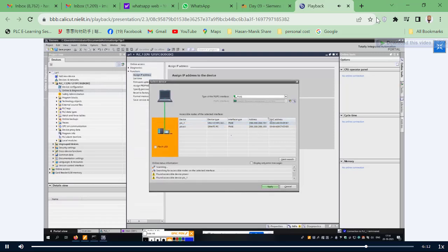So this 205 is there. You see 205. That 205 is another PC. So in this network, one person is using a PC. That is a PC address. Now, this is my PLC address. For example, by default some XYZ address will be there. Then using this MAC address, some XYZ comes. Then you can assign, because once you create the project, this will be loaded. Apply means overwrite. This old address will be gone and your new address will be updated. That's all, sir.